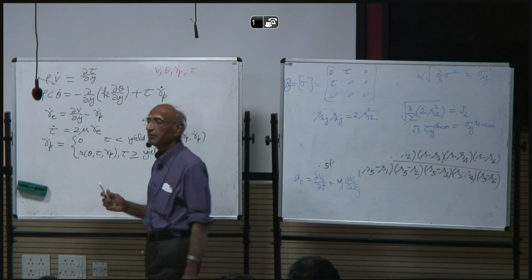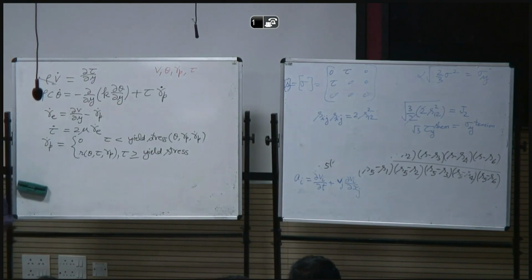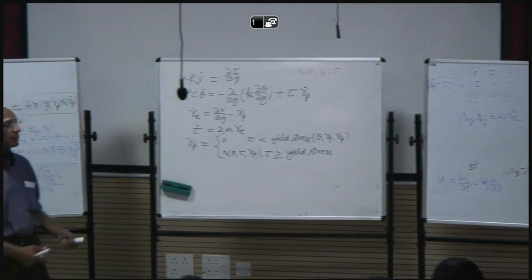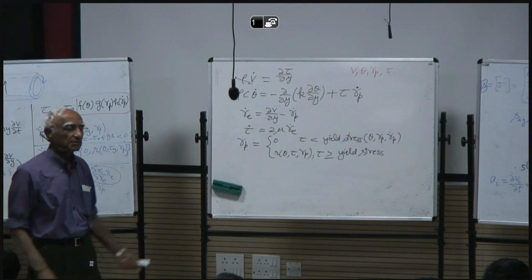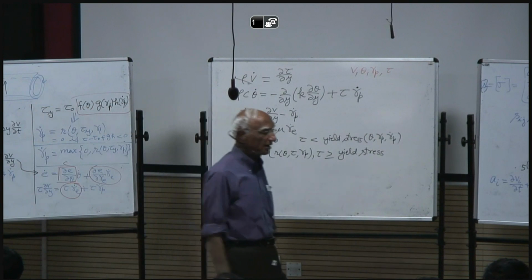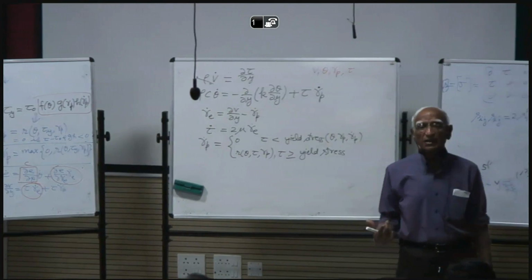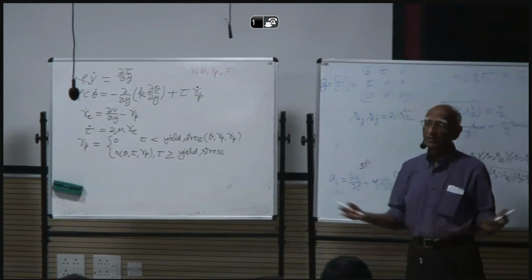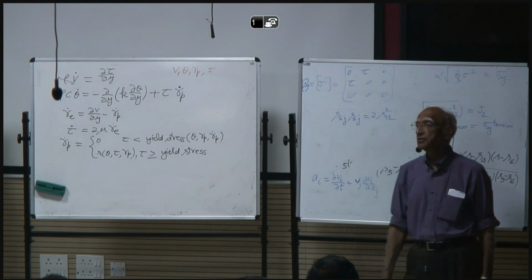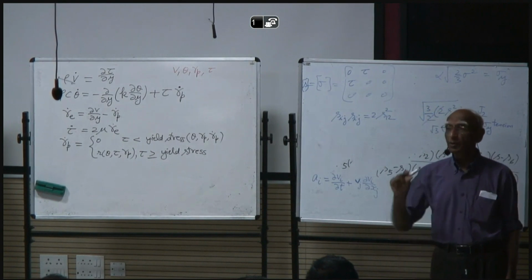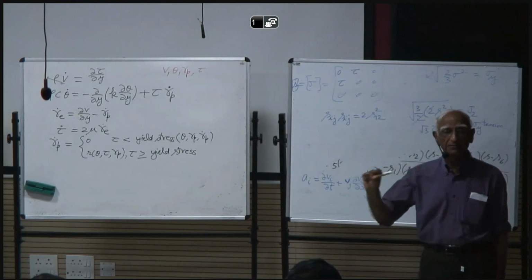So there will be an instability occurring when the material can no longer support this load you are applying or the local stresses. So the strain rate locally will start becoming very large, and you will see what you may call a shear band, because locally the deformation will be very large.